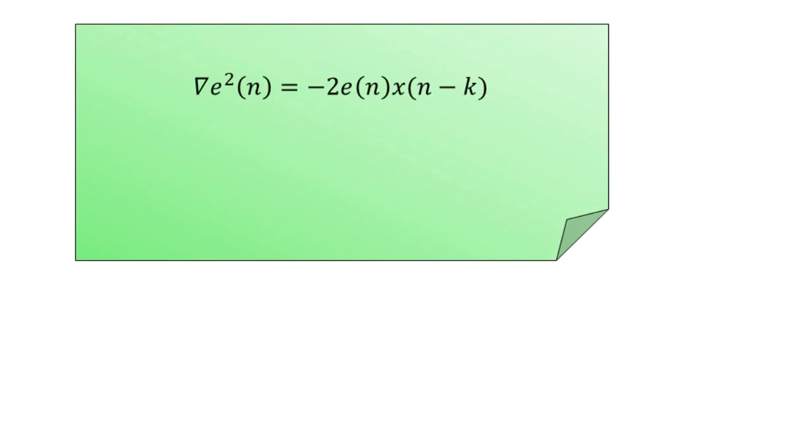These rules are based on the premise that if the sign of the error signal multiplied by x(n minus k) is changing frequently, then the coefficient w(n) of k should be close to its optimum value, where the gradient is equal to 0. If the change of sign is not observed to be frequent, then the coefficient w(n) of k is probably not very close to its optimum value.